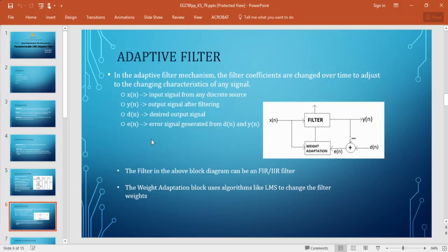The second filter is the adaptive filter. It has the ability to adjust its impulse response to filter out the correlated signal in the input. It requires little or no prior knowledge of the signal and noise characteristics. If the signal is narrowband and noise is broadband, no prior information is needed. Otherwise, they require a signal that is correlated in some sense to the signal to be estimated.